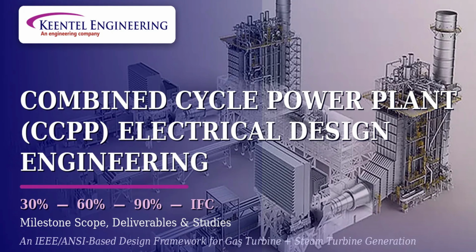Welcome to Keentel Engineering. Today, we are covering the electrical design engineering framework for a combined cycle power plant, a milestone-based process running 30% through 60, 90, and issued for construction. The site basis is 13.8 kilovolt medium voltage, 480 volt low voltage, and the IEEE and ANSI framework. The Keentel position: grid interconnection is a first-order design input, not a downstream utility formality. We anchor the interconnection basis at 30%.